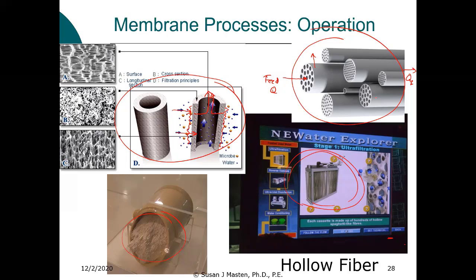And we did have ceramic filters. We could have boiled it. It would have taken a lot of time, though, and a lot of energy. And we had not a lot of time to get to the next campsite. We could have let some of it settle. That would have taken some time, too. We actually did some of it when we had time at night. We actually pre-filtered it through fabric filters. So we just made filters out of handkerchief type material that we had brought specifically for that purpose. So we pre-filtered it through the fabric filter, then filtered it through the ceramic filters, then added the chlorine tablets.